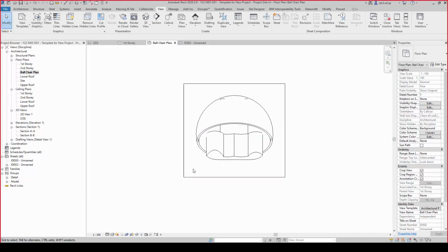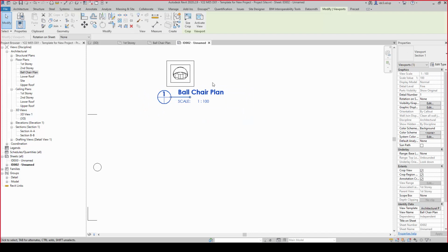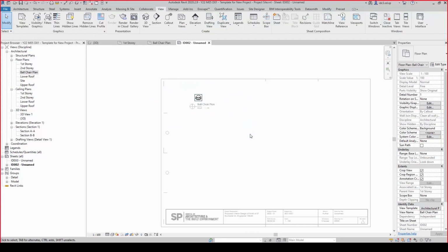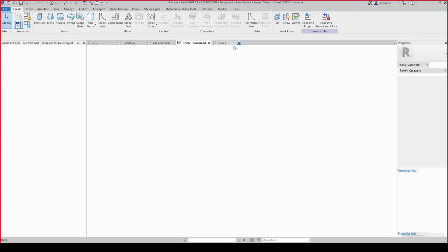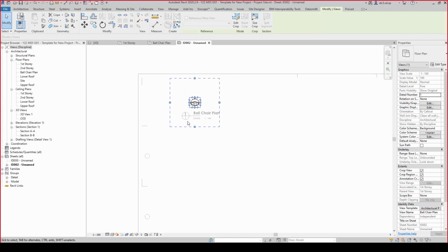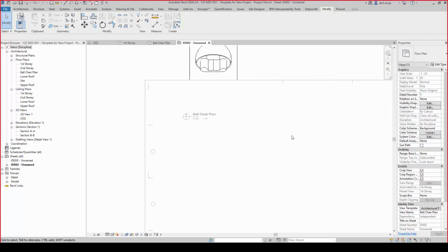We will not be able to see too much difference here, but when we go into the drawing sheet, we should be able to see an update. Okay, it is still not showing up here. So what I'm going to do is, I am going to try again and do it from here. Alright, and click on the architectural plan and change this one to 1:15 scale. Can I do this? Nope, there is no 1:15 scale here. So I'm going to try my luck with, let's say, 1:20 scale then, in this case. And I will click apply and OK.